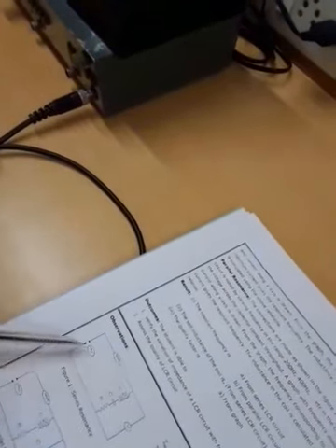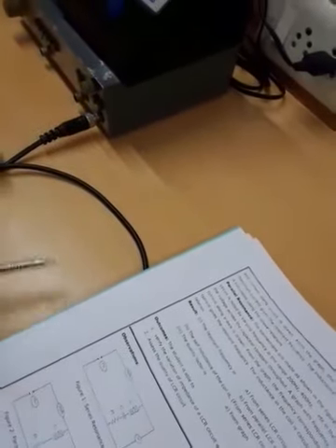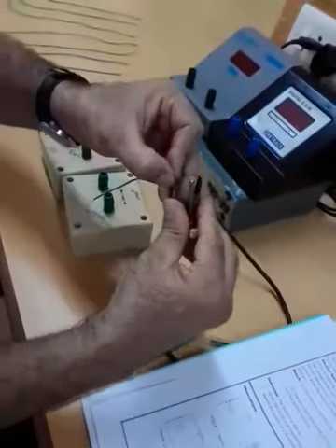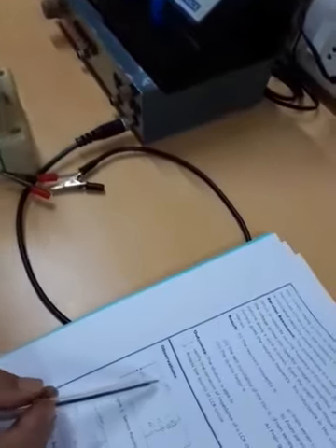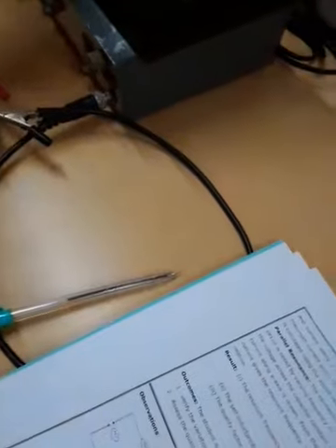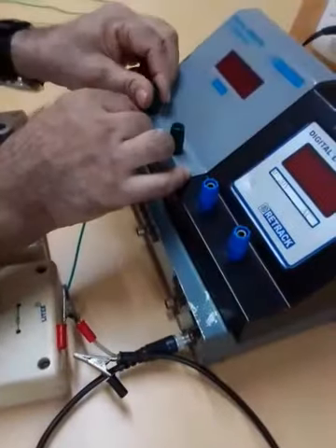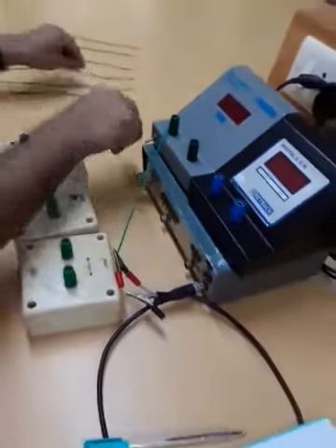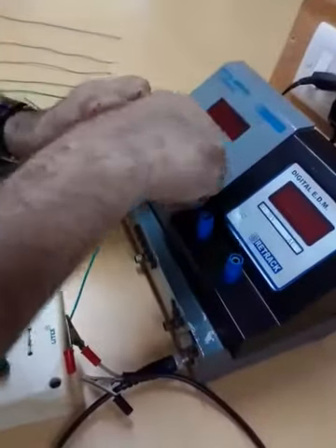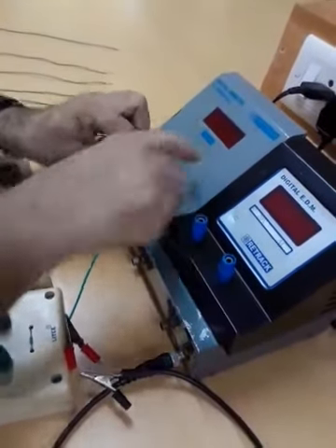So we have to start from the signal generator. From the signal generator we have a wire and try to connect a wire to that. From there you try to connect to the positive of the milliammeter, one end of the milliammeter. Then from the opposite end of the milliammeter you connect this to the inductor.